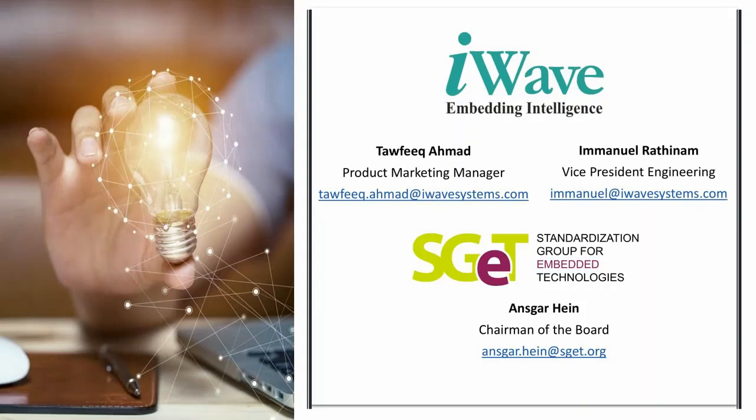And another question from Uvis: are you providing an application note to solder properly the SOM and what is critical? Definitely yes. For all our modules, we have the detailed design guide, correct? The design guides will provide all the stuff: how you have to design a carrier board, how to put the OSM module, how to put the pins. You can also make use of our free support for reviewing your schematic, especially on the OSM pinout area. We can also review your layout, your mechanicals, and make sure nothing goes wrong. So that level of support we can always provide.